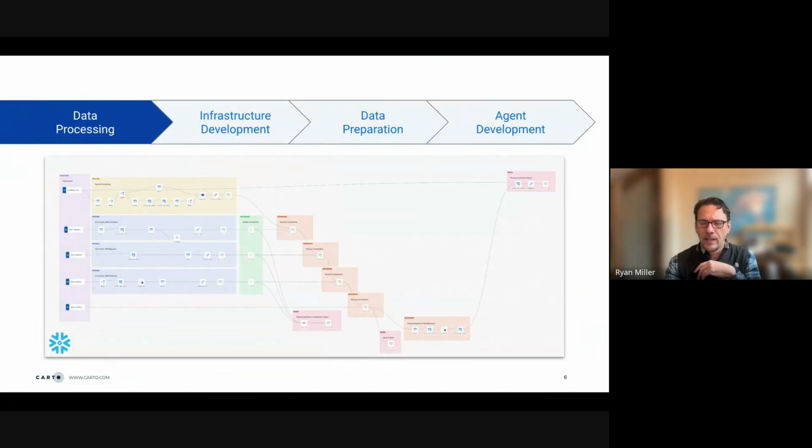All right, so a little bit on the processing pipeline. This is a schematic of our workflow environment that allows you to build out these geospatial data processing activities. We've got our data sources on the left. Those would be things like, as we mentioned, parcels, topography, hydrography, streamlines, riparian areas, etc. And we're doing different sorts of operations like buffers, filtering based on attributes, and then we're basically differencing them.